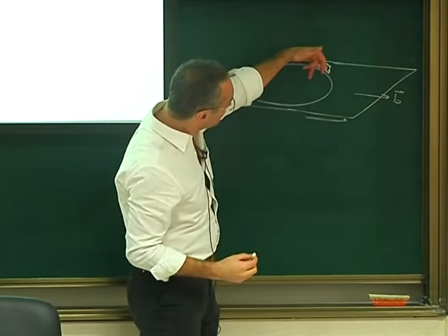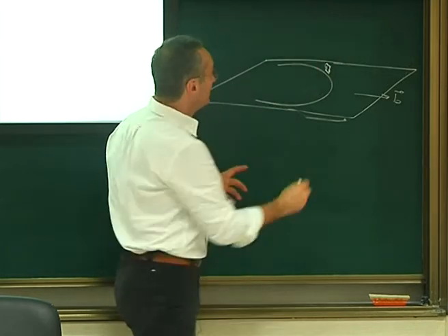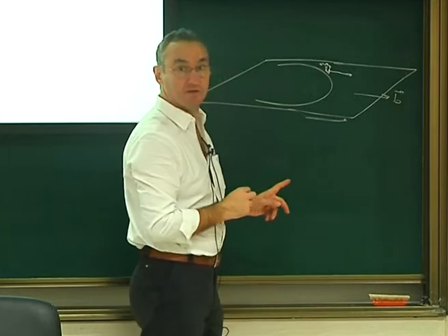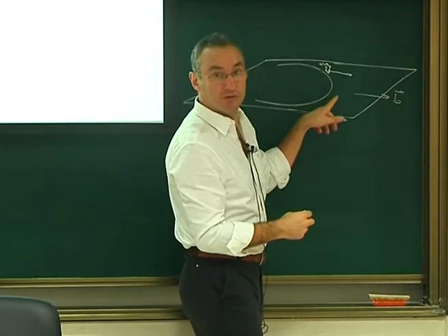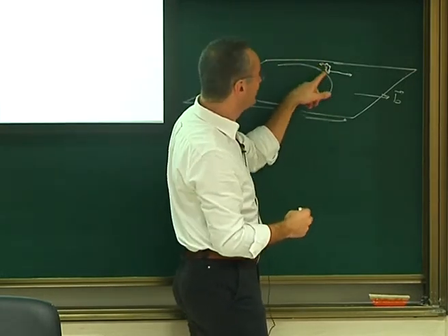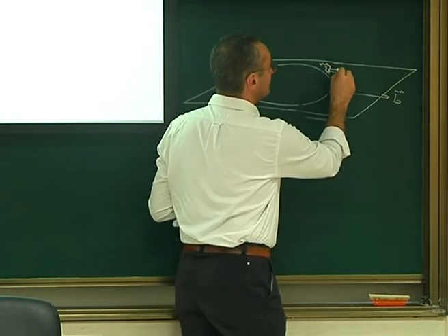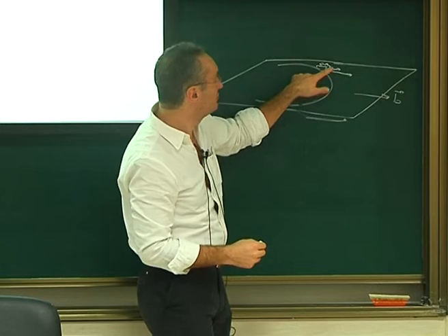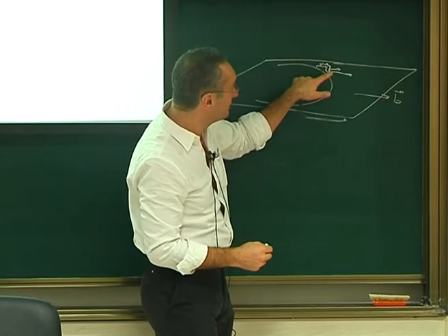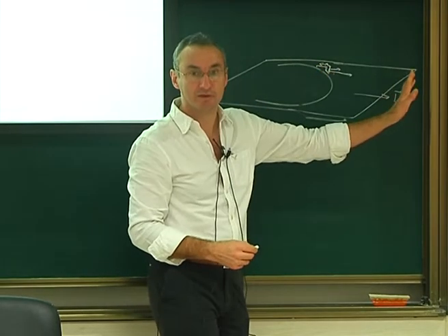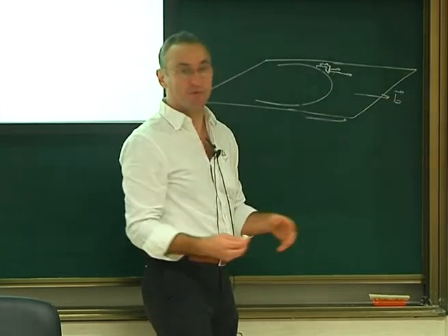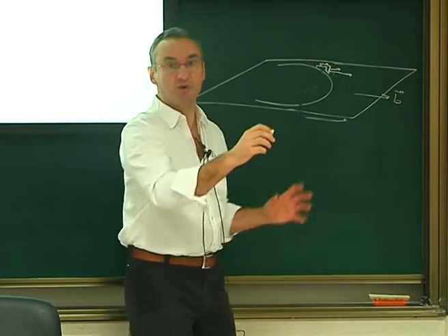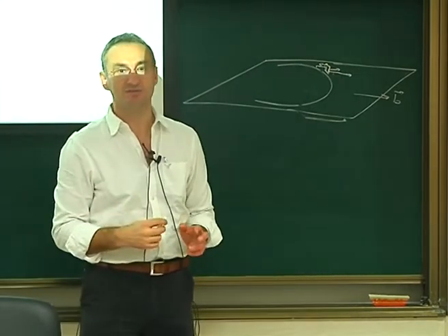Just because of the local interactions between the dislocations and the prismatic loops, here you will have a stress that will be a lot higher than there, although this is negative, okay? It will be of opposite sign because I agree, the sign of the loop is opposed. So here and there, the force will be opposed. The same for this one. But this one and these ones will be, let's say, at the same distance from the loop. So those will compensate, more or less. This will be higher. So because of this higher stress, it will move. Okay? This is the idea. There is what I call a gradient. Since you have a gradient of stress between the top and the bottom, then the biggest one will drag the whole. You see, this is the mechanism.